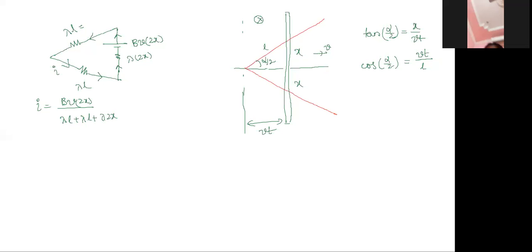Can you tell me what is I2? Eta times I1. Yes. So flux initial is equal to flux final again. The inductance doesn't allow the flux to change. So L into I1 is L by eta into I2. So I2 is equal to eta times I1, where I1 is equal to E by R. So this is the story at t equal to 0.